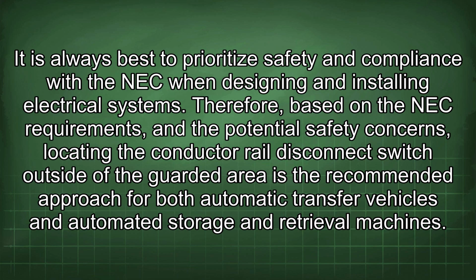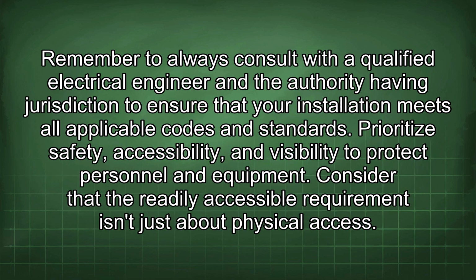Therefore, based on the NEC requirements and the potential safety concerns, locating the conductor rail disconnect switch outside of the guarded area is the recommended approach for both automatic transfer vehicles and automated storage and retrieval machines. Remember to always consult with a qualified electrical engineer and the authority having jurisdiction to ensure that your installation meets all applicable codes and standards.